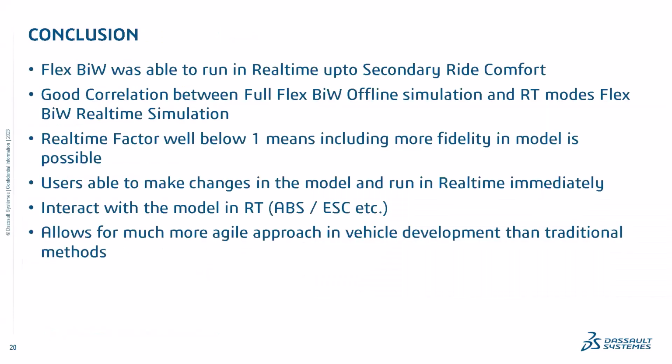In terms of the conclusion, I would have liked to show you more results on this one, but I didn't have it until that time. But the top mount was one of the most important ones anyway. So flex body in white was able to run in real time up to second ride comfort. There was a good correlation we saw between full flex body in white offline simulation and RT modes flex body in white real time simulation.